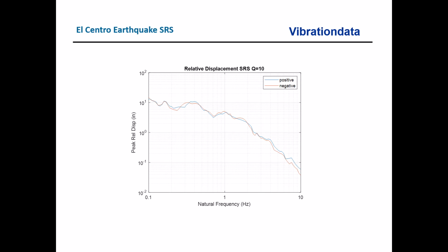Now, do we want a structure that's going to have to withstand that relative displacement? Probably not. So there are some very real-world trade-offs that come into play, and I'm not telling you what natural frequency to choose for your design goal, because I'm not that smart. But I want you to be aware of all the trade-offs involved and all the considerations.